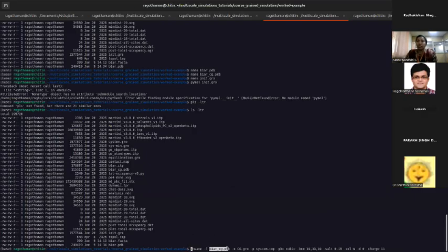Here I'm giving the modified, or CG-converted, PDB file, and I'm giving the output file as cg.gro. I'm using the same topology file, and this is the periodic boundary condition. This ensures that there are no jumps between the molecules, so that when the molecules move from one side of the box, they come around from the other side. The number of particles within the box in which we are simulating remains the same throughout the simulation. The shape we are choosing here is a cubic box, and these are the XYZ dimensions. We can modify them as per the size of our protein structure.